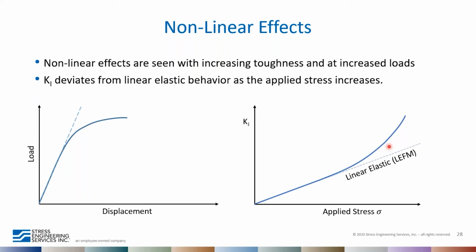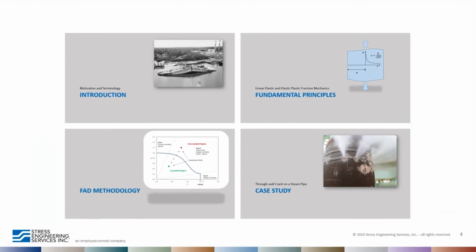And so, basically linear elastic fracture mechanics underestimates the conditions or the energy at the crack tip because it cannot and does not account for energy associated with plasticity and some of those other non-linear terms. Okay. As far as determining the J in the nonlinear range, finite element analysis is a good tool for doing that.